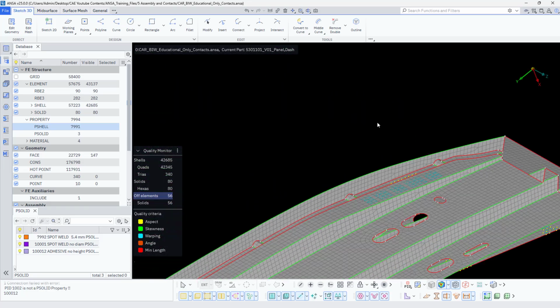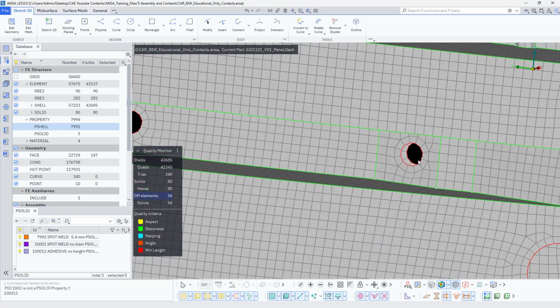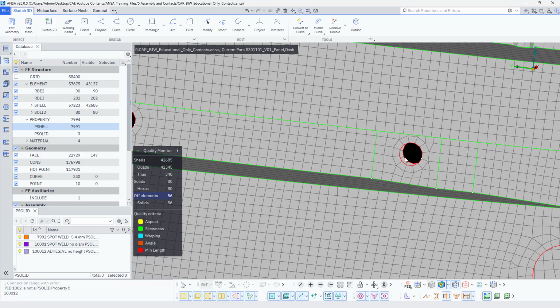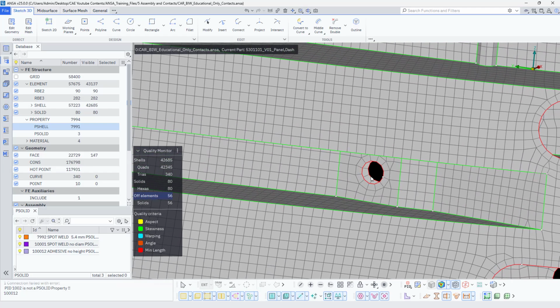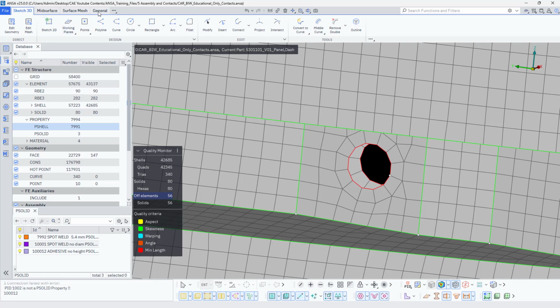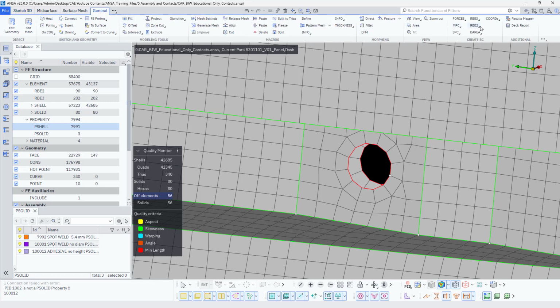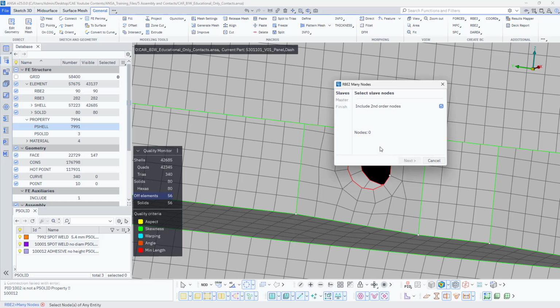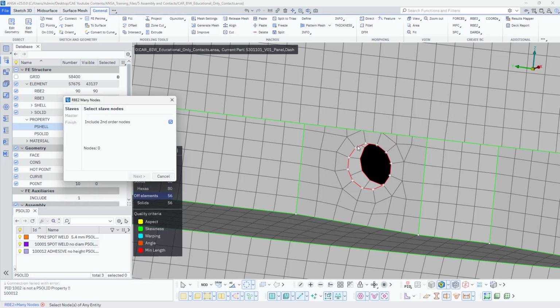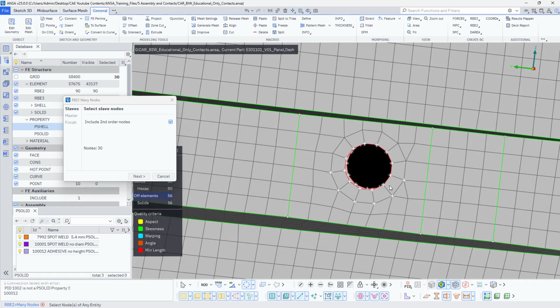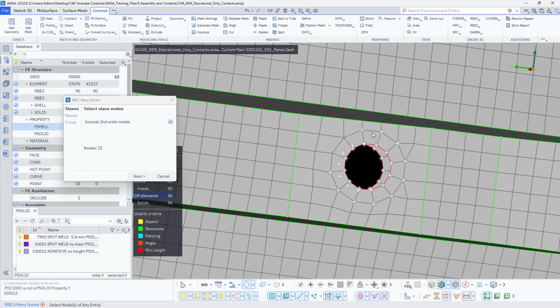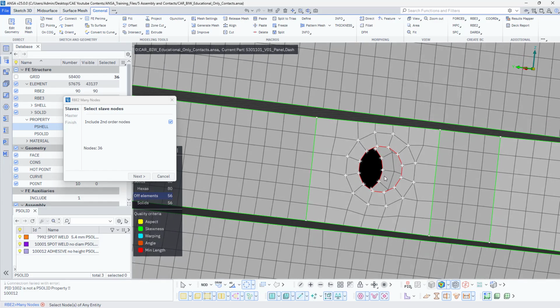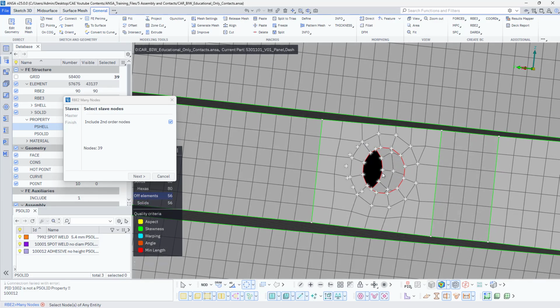And one more important thing is how we define the screws and also representation. So if you would like to join these two, you can utilize the RBE2. You can switch to here many nodes. So usually for this cases you can activate this one, closed loop, select these two and even these. This is important because for that only we create two layers so that the representation should be proper.